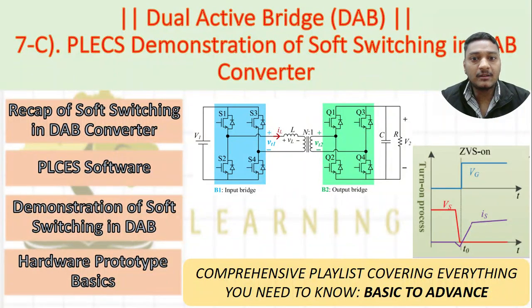What are the reasons that soft switching does not happen when m is greater than 1 or very much less than 1? And why at m equal to 1 we have really luxurious soft switching for both the bridges, and it will work perfectly fine. All these things we have discussed in the previous two videos.